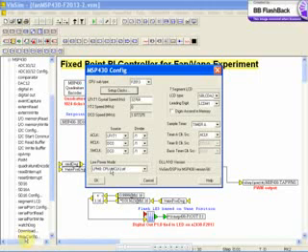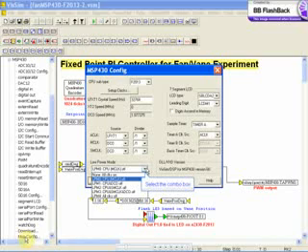Based on your clock setups, you can see their values here. You can select a source and divider for the auxiliary, main, and sub-main clocks here. The available sources depend on the CPU subtype selected. Here you can select clock sources for timers A, B, and the basic timer. Their availability depends on the CPU subtype. You can select 6 different low power modes ranging from none to turning off all clocks. As you turn off more clocks, the power consumption decreases.